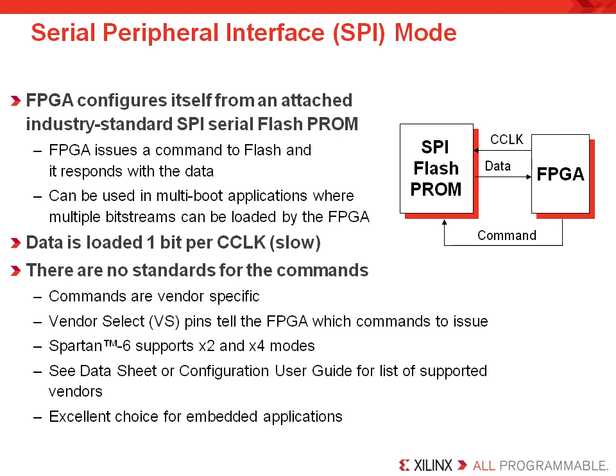In Virtex FPGAs, the FPGA requires the vendor select signals, that is the VS, which is 3 bits wide. These bits are used by the PROM to determine which vendor's SPI flash PROM is being used and which commands to issue.